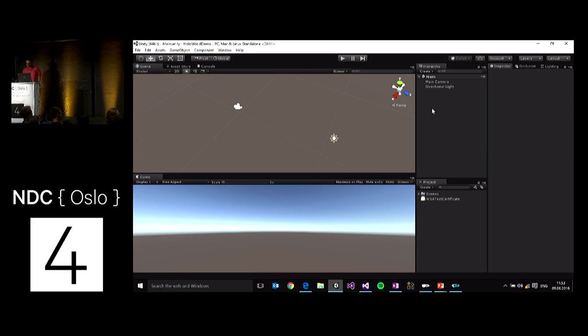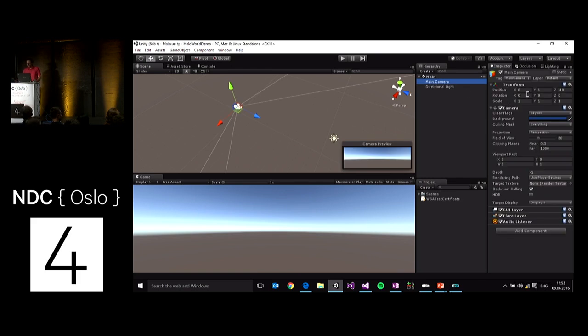The first thing we need to configure for HoloLens is the main camera, because in a fresh new Unity scene, the camera has a set position of 0, 1, -10, which can cause an offset if we use it for the HoloLens. Like I said, if the user walks around with the device, the position of the device is mapped to the main camera in Unity. So we don't want an offset here, so we set it to 0, 0, 0. And also the head rotation is mapped to the camera rotation. Okay, so we set this.